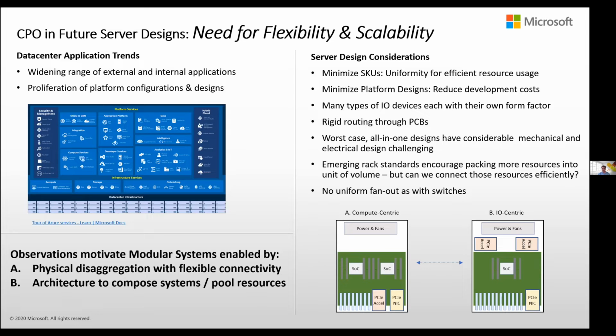And these platforms, it's important to note that they're quite different relative to the Ethernet switches, right? If you look at some of the Ethernet switch designs and considerations of optics and optical integration, the nice uniform fan out is not the opportunity that we have here, right? We're looking at all kinds of front to back and back to front and crisscrossing of PCB traces, all kinds of messy scenarios, just to be able to design all these things into as few designs as possible, right? So those are some of the considerations that we have in mind.